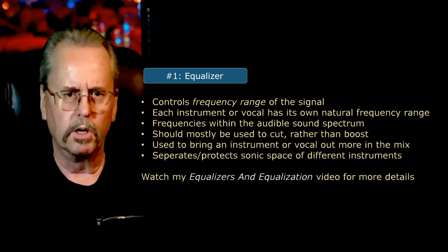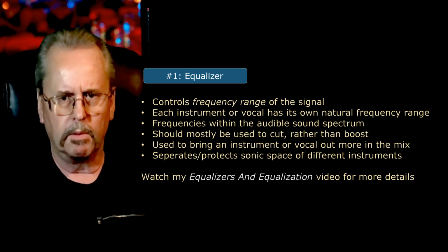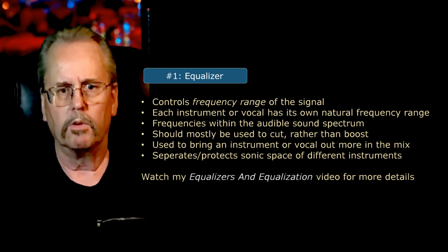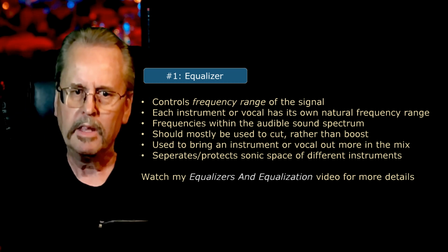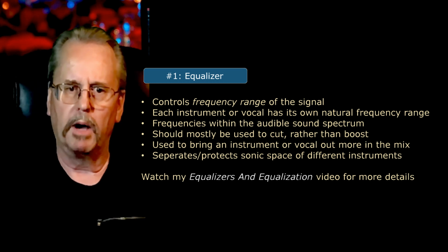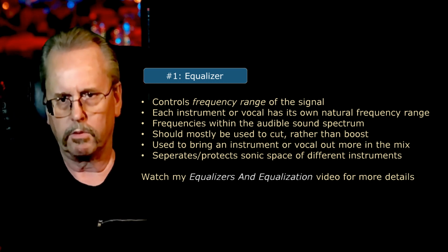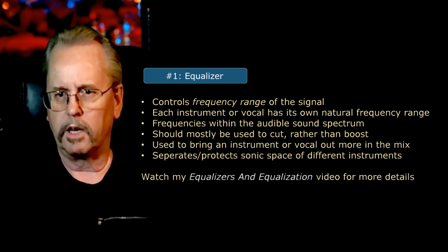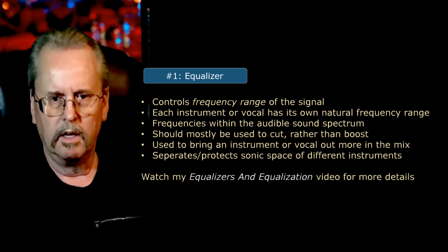Equalizers can be used to boost frequencies to bring out specific instruments or vocals, but more often they're used to cut certain frequencies that may be interfering with a given instrument's natural sound or sonic space. Skilled sound engineers live by the rule that equalization should seldom be used to boost frequencies. Rather, equalizers are more often intended to be used to reduce or cut unwanted frequencies.